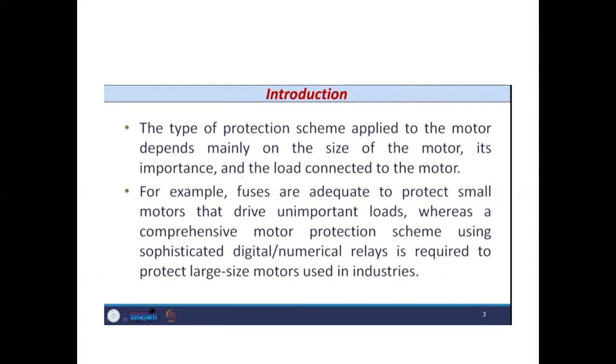Whereas if I use the induction motor at 6.6 kilovolt, or in some auxiliaries in large industries and large generation power plants, then in those cases we need to give separate sophisticated digital or numerical relay protection, so that if any fault occurs, it can be easily detected.